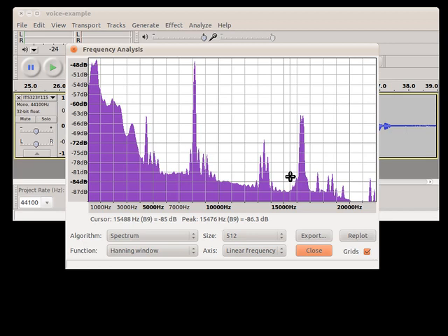Bandwidth, most of the energy is around 3 kilohertz, maximum of about 20 kilohertz. But in fact, most of this is quite weak in terms of signal strength. So that's going from the microphone to the wireless transmitter, an analog signal containing the analog data. The wireless transmitter in my pocket also transmits analog signals to the wireless receiver here. So this was a wired medium, the first one. Here, we also have an analog signal.